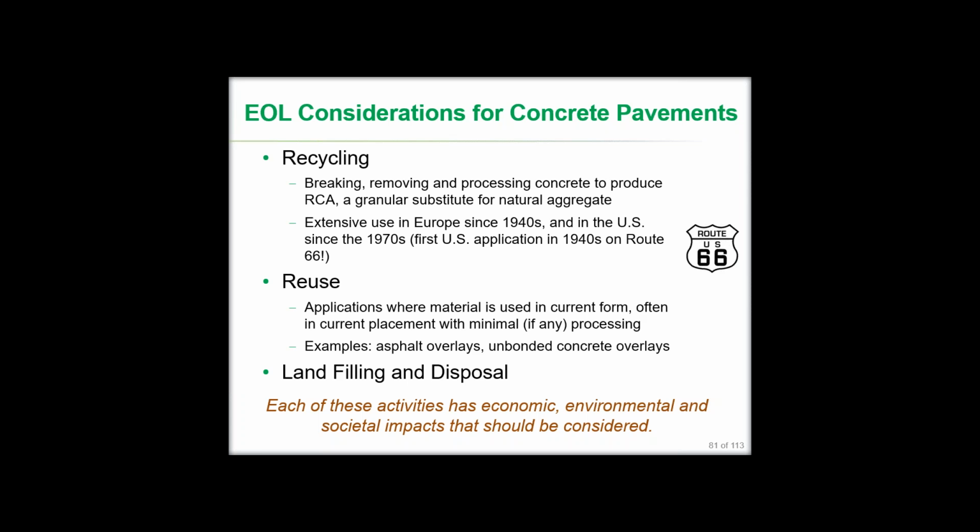Pavement reuse, applications where we're using that material in its current form, usually in current placement, not picking it up, although possibly picking it up and moving it, but generally in its current form with minimal, if any, processing. Occasionally some processing in place, rubblization being one example that is still considered to be reuse as opposed to recycling when you're leaving it in place, and we'll talk about that in a bit as well. And applications for reuse, examples of the various types of overlays.